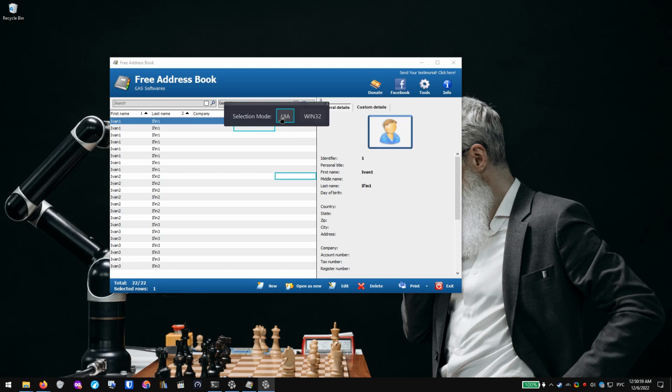As you can see, once the Selector Explorer was started, the elements of the window started to be highlighted. That means you can actually select the specific element. Let's select the Tools button, for example. In order to select the element, you need to press and hold the left control key and press the left mouse button on it.